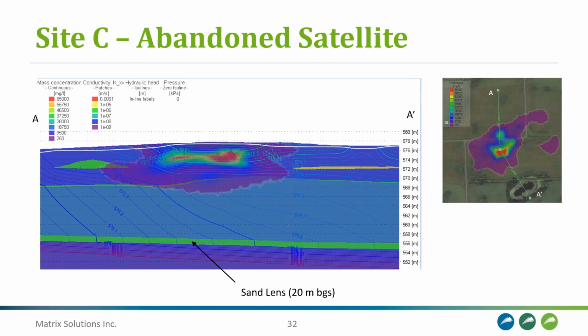So the results of the site-specific risk assessment, we were able to eliminate the livestock watering and irrigation pathways due to unsuitable background groundwater quality. We also did numerical modeling simulations that showed very little lateral spread of chloride with no impacts to the freshwater aquatic life in adjacent wetlands. There just wasn't that spread toward those wetlands. And so we're really left with the root zone impacts at this site as well.